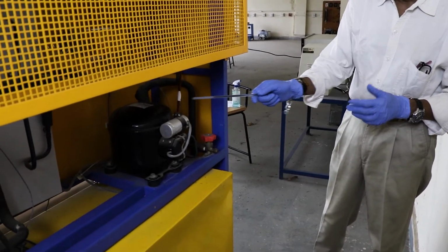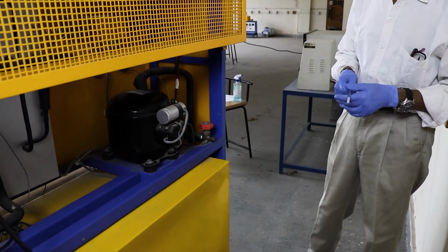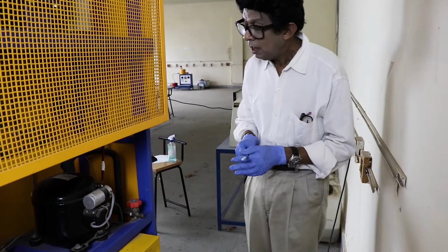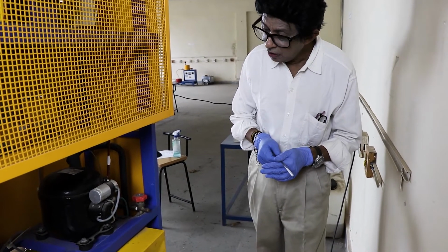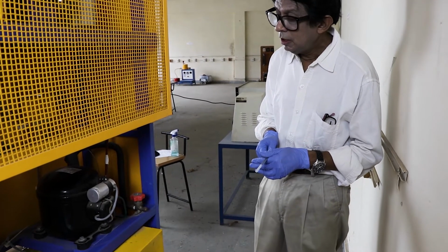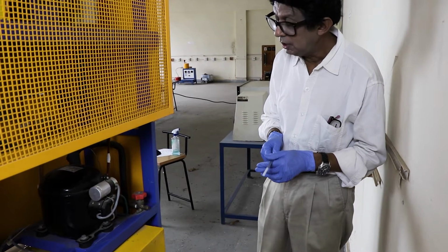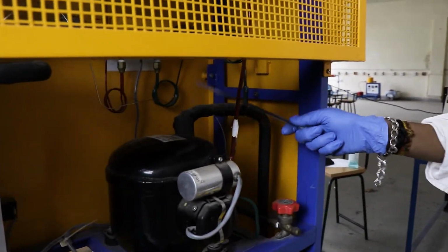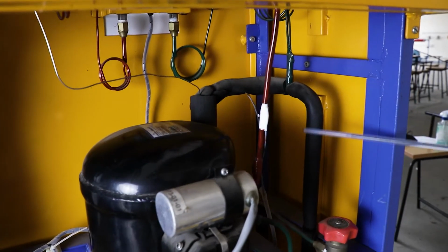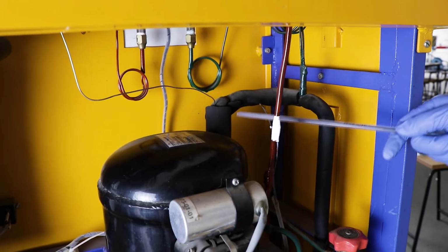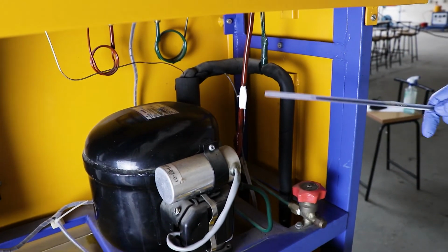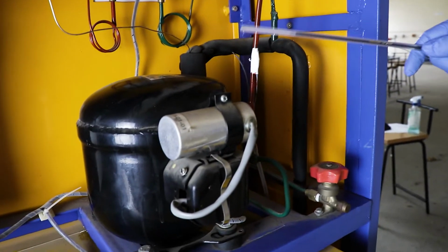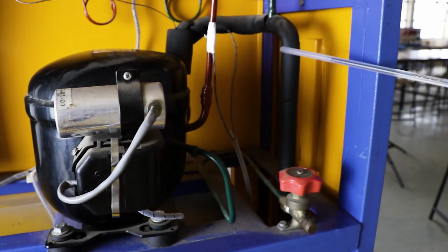It has got the reciprocating compressor, which is mounted on the same shaft as that of the motor. Motor is also inside this only. Now the crankshaft of the compressor is the shaft on which the motor is mounted. Now look at this black one. This black one is the inlet or the suction of this compressor, this insulated one, because this is the suction of the compressor, and this red one is the exit of the compressor. These are the two pipes which are connected to the compressor, the suction and the exit.